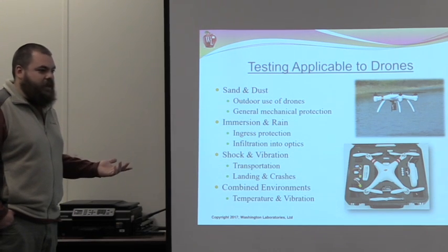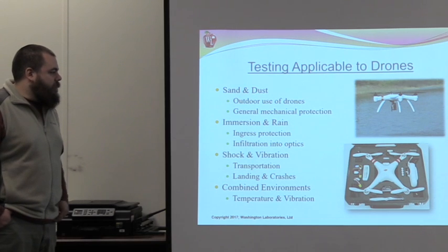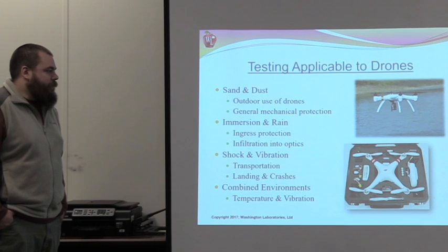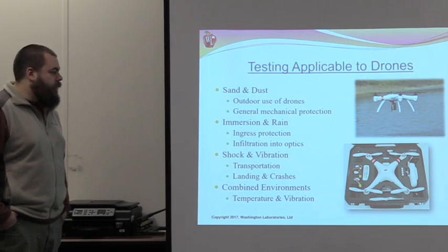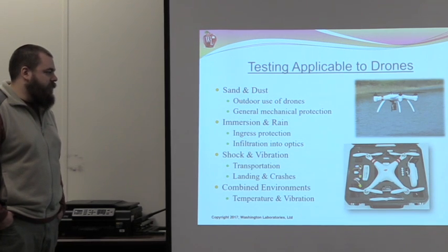It might see 0 degrees Fahrenheit. So you kind of have to take into consideration how your packaging handles that. If the drone is left in the backpack overnight, the plastic is going to be significantly more brittle in the winter, and you may have warranty issues with things breaking.